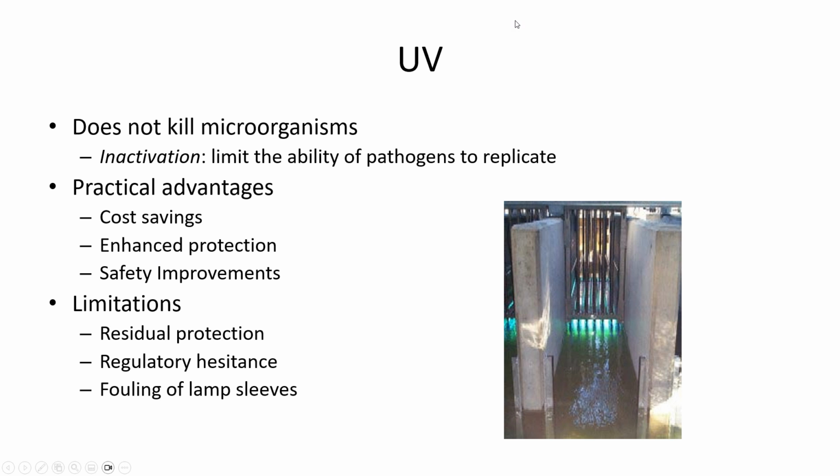They can't protect themselves against the UV. It penetrates through, and it's able to inactivate things like Cryptosporidium that otherwise would be really difficult to provide protection for. So you can use a complementary approach of both UV disinfection and also chemical disinfection.